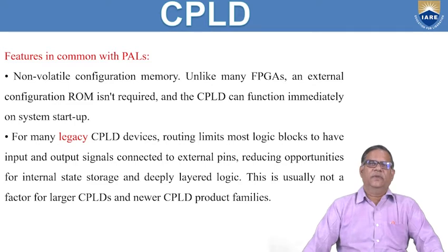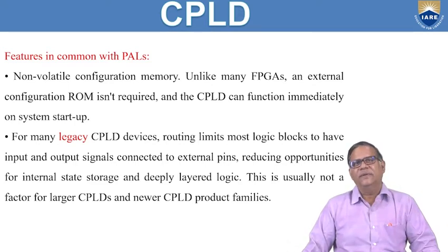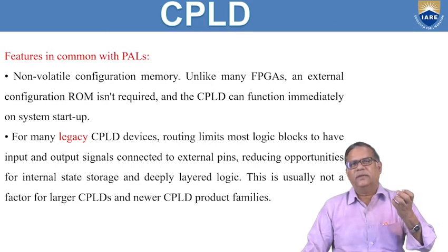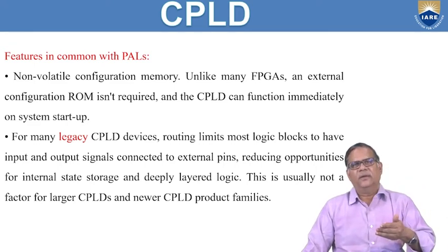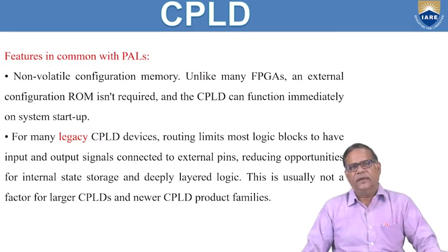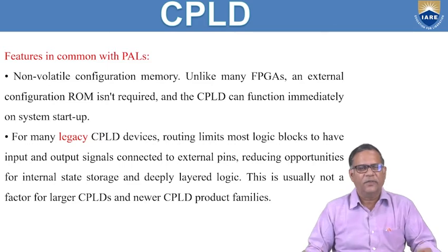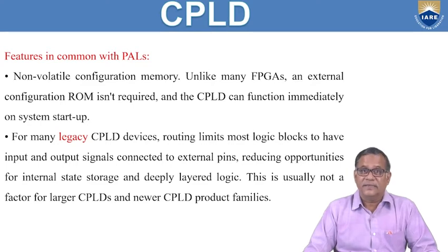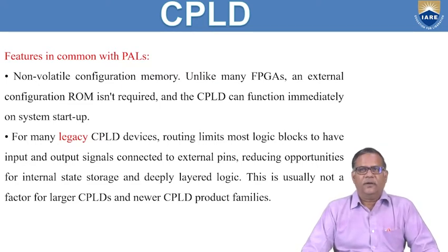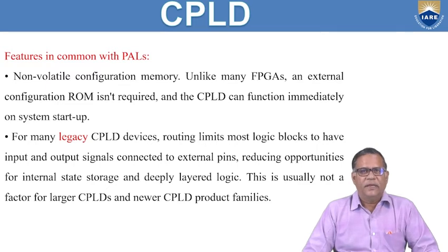Unlike FPGAs, where the programming data or the bitstream data is stored outside the FPGA in a PROM, and every time you power on, the bitstream is loaded into the FPGA and the FPGA gets configured, and the moment you switch off power, the FPGA becomes blank. But in a CPLD, the programming is inside, in a non-volatile configuration. So here we don't require a ROM, and the CPLD can function immediately after the system is powered on because it has built-in non-volatile storage.